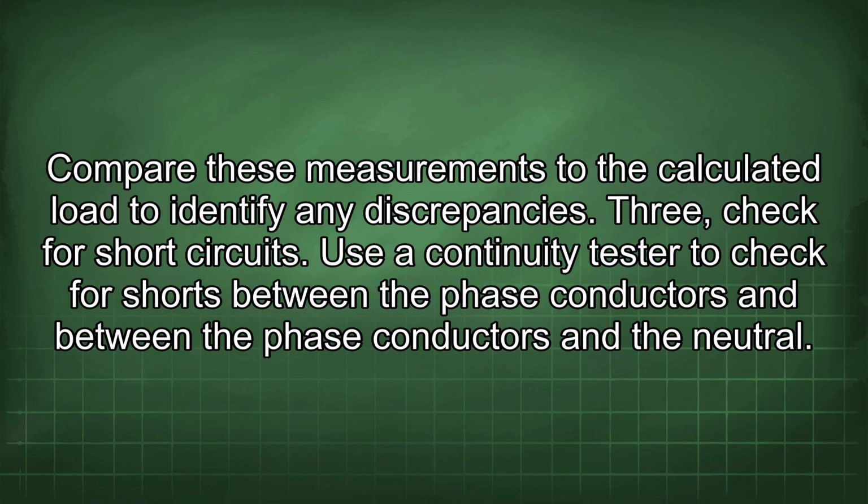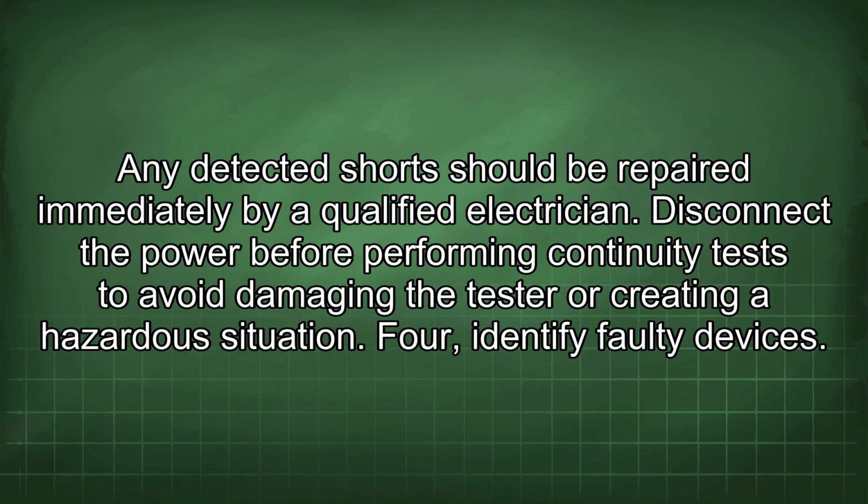3. Check for short circuits. Use a continuity tester to check for shorts between the phase conductors and between the phase conductors and the neutral. Any detected short should be repaired immediately by a qualified electrician. Disconnect the power before performing continuity tests to avoid damaging the tester or creating a hazardous situation.